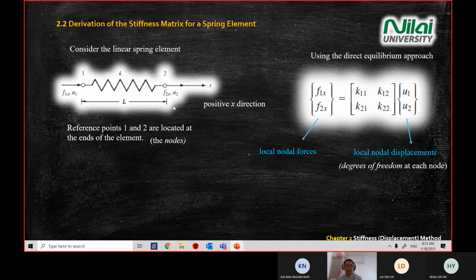If you look at a single element, then use a small f for your force and small k for the stiffness, and remember to change your displacement into the direction. Don't use the small d. Change it to the direction. For example, if your structure goes in the x direction, then you use u, for y you use v, and for z you use w.